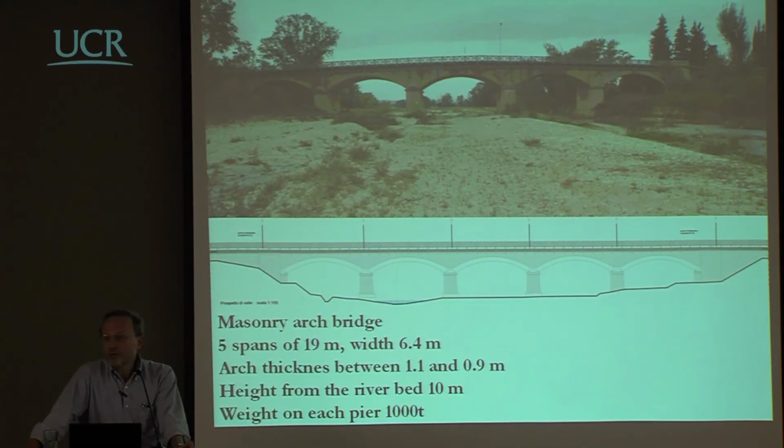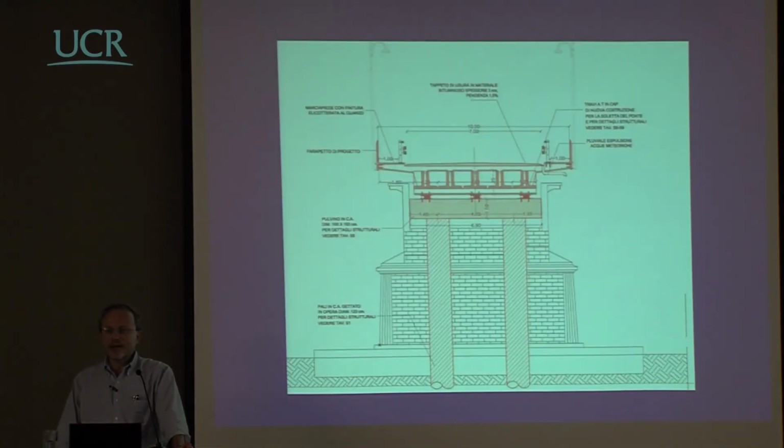it's also designing it. It's a difficult task. What we did was to design a new one. Of course, you cannot modify the bridge because it's protected, because it's a monument and so on. So what we did was to design a completely new bridge, having 2 large diameter piles drilled within each one of the existing piers, and then a transversal beam in the thickness of the non-structural part of the bridge, and then some isolators here, and then a concrete deck.